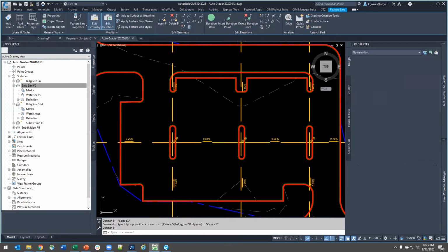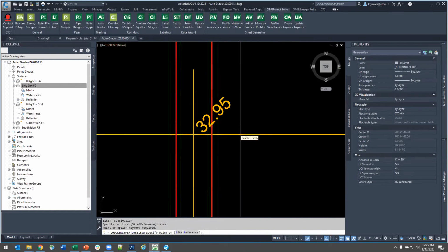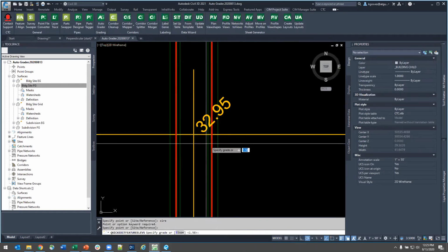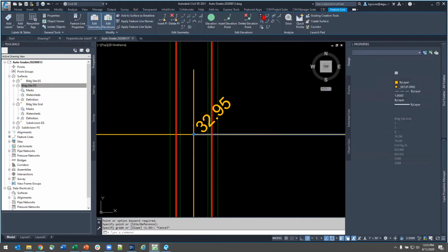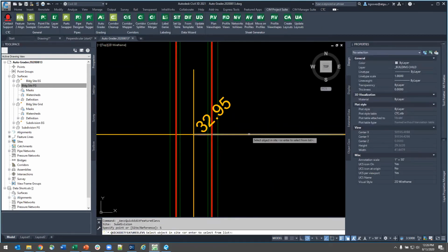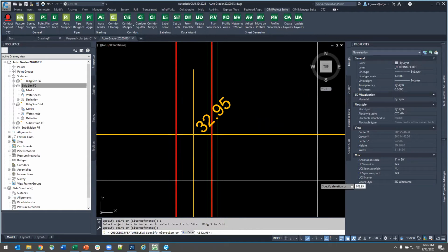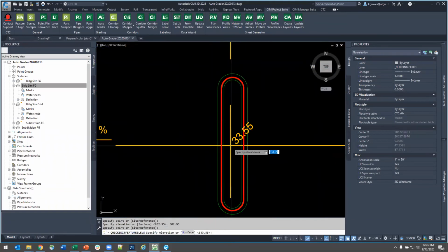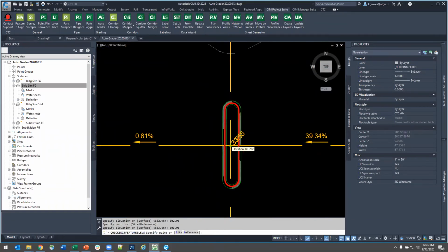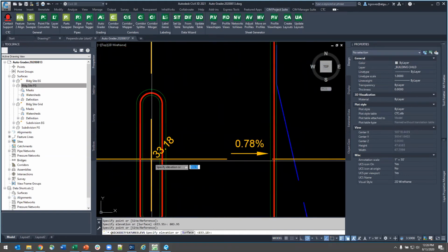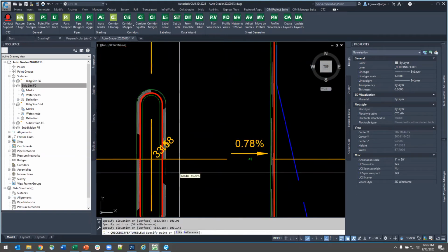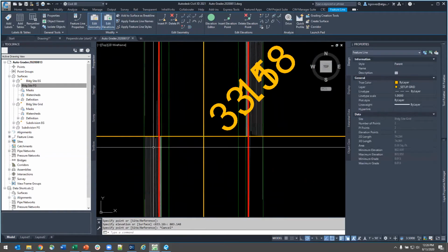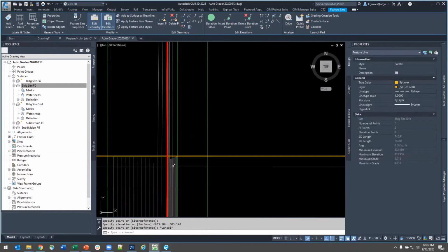I'll make this really, really drastic, but I'll change the elevation of my setup surface by using my feature line elevation edit. I'm going to confirm that I'm in the right site here. So it's 832.95. I'm going to make this really, really obvious. I'll go 802.95, 803.95, 803.18. So I should now expect to see some pretty drastic elevation changes over there.